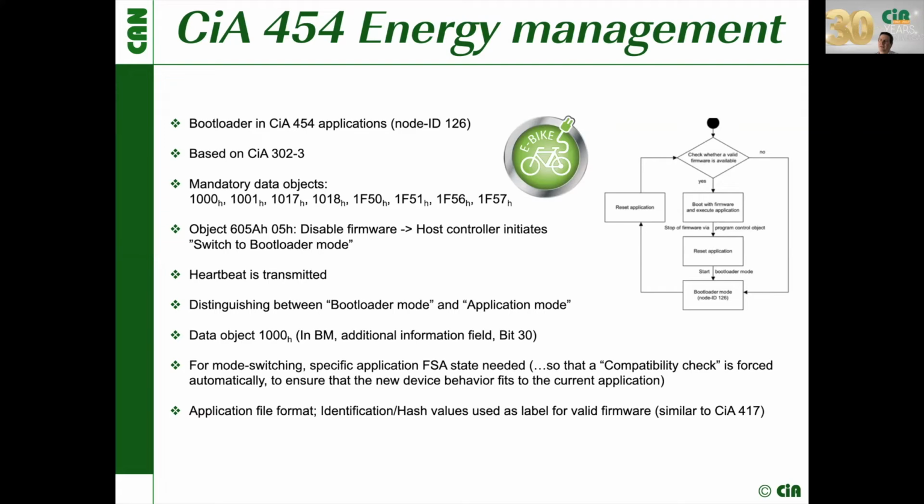And the next thing where we have a differentiation is we have a certain link to the application state machine of the energy management system. So in the energy management applications according to 454, there exists a certain state that is called compatibility check. So any device in CiA 454 that has received a new application program and that is requested to start this application program shall then pass the compatibility check.